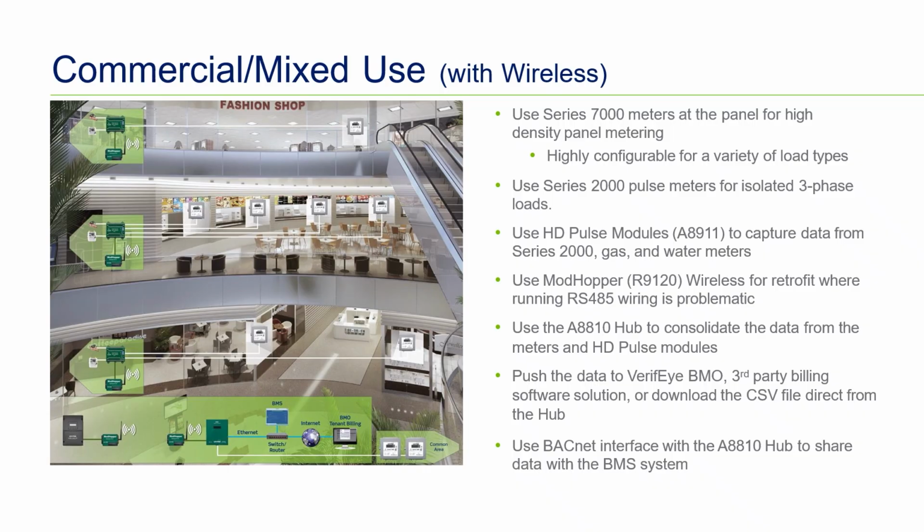Use the A8810 hub to consolidate the data from the meters and HD pulse modules. Push the data to VerifEye BMO, third-party billing software solution, or download the CSV file direct from the hub. Utilize the BACnet interface with the A8810 hub to share data with the BMS system.